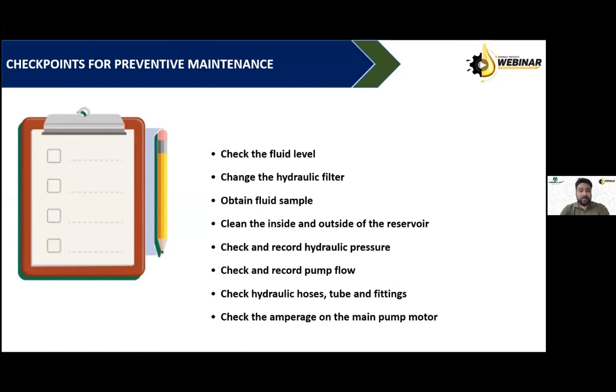external lab. Clean the inside and outside of the reservoir so that you have a neat and tidy environment. Follow 5S whenever you do any maintenance activity. Check the records of hydraulic pressure, because this would certainly be a part of your quality program as well. If the hydraulic pressure is not maintained, probably your end job would not be sufficiently good. Check and record the pump flow rate, because if the pump flow rate is going down, there would be certain reasons for it. Check the hydraulic hoses.